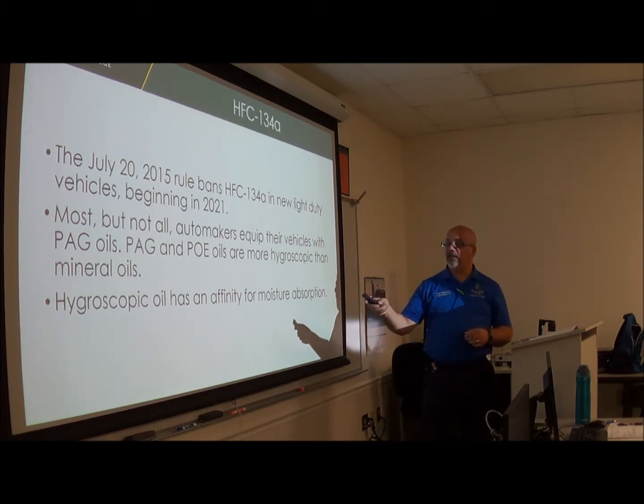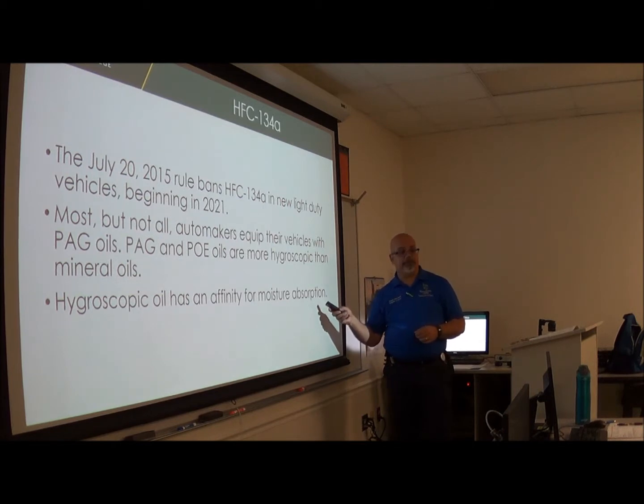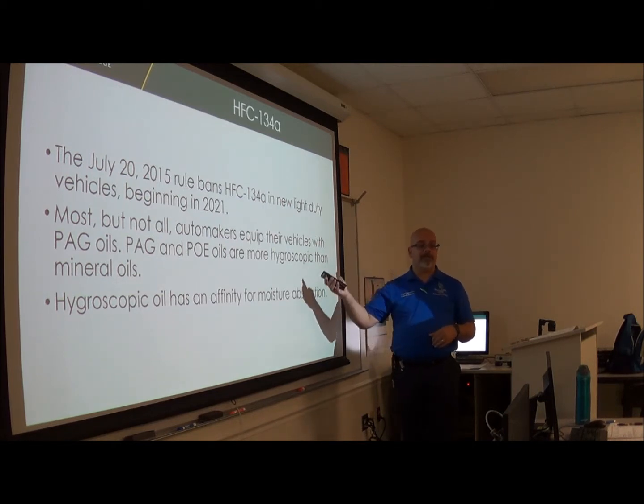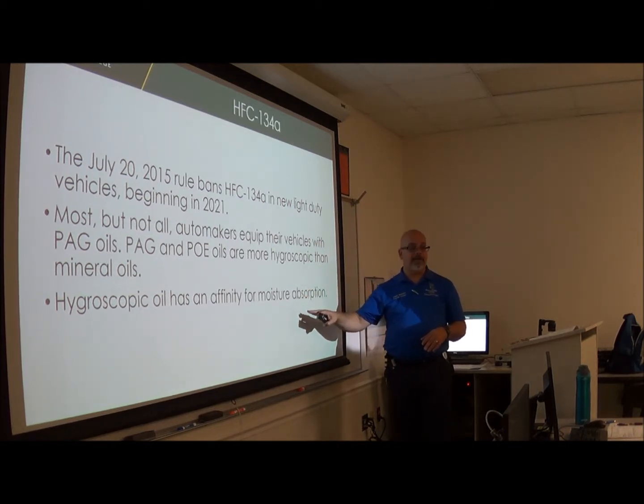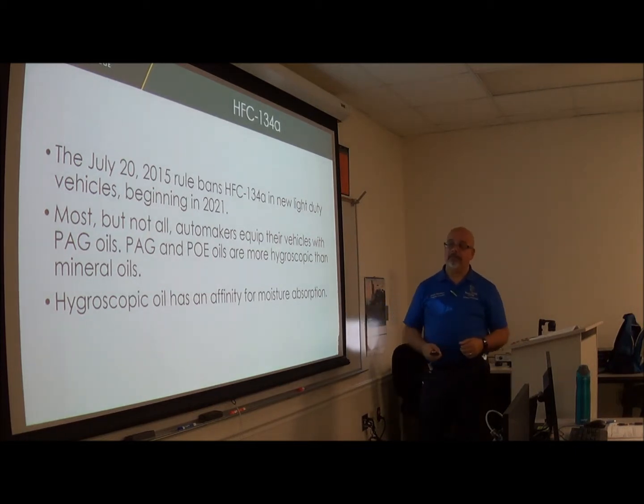Hygroscopic oil has an affinity for moisture absorption. If you remember in a few slides before, I mentioned that we have to eliminate moisture from the refrigerant. Okay. And that's one of the jobs that the dryer does. But if it has too much, that's what happens.